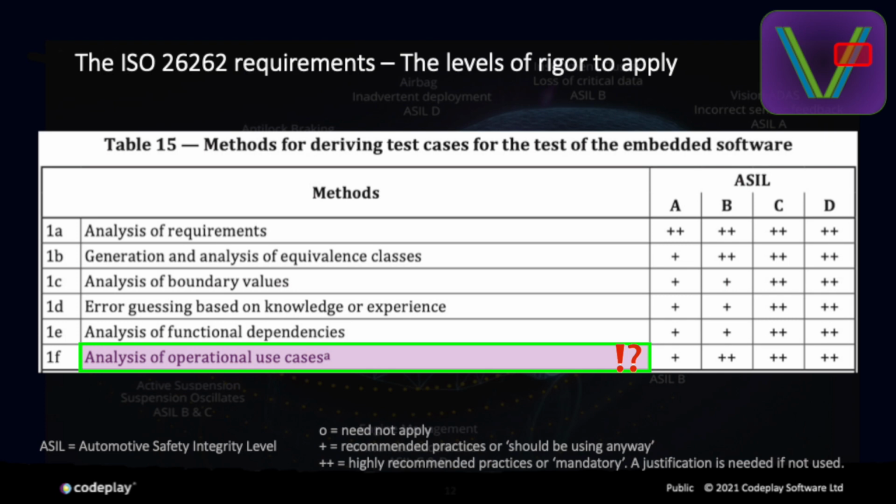As part of one or more types of self-tests, it is very likely that hardware and sensors will be included in these tests. The important point to note here is they're performed on a defined regular basis, which may mean the application needs to time slice the test to fit in with normal operation or interrupt itself. If there is time within a cycle, this shouldn't be a problem. But if we're cutting it close to the mark, and there's not enough time, then the stack has to be forced to interrupt. And this could be problematic in the middle of the execution of a kernel, for example.